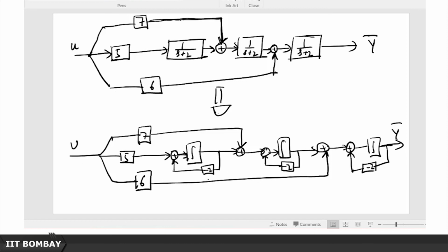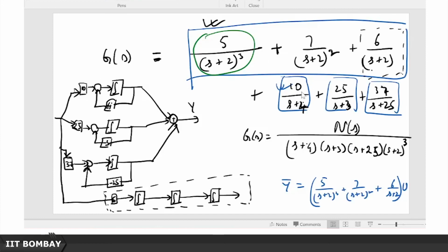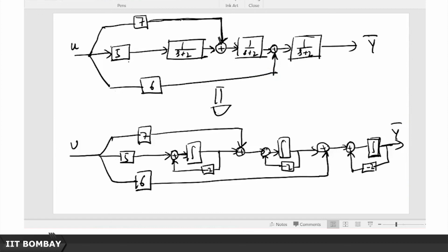So I have actually again used only op amps as gains, summers and integrators, and I have realized this. Of course the compromise here is that I have not really realized it in the perfect diagonal form, because I simply cannot. So how does this help this part at least? The remaining part of the transfer function, that state space realization, isn't very interesting. So let me just talk about the realization. Let us ignore this part, because this part is just diagonal. I can totally see how this is going to behave. So let me just talk about how this part, the state space realization, looks like.